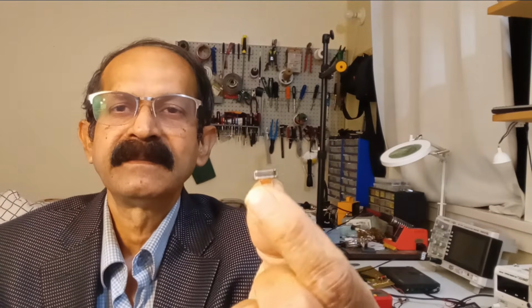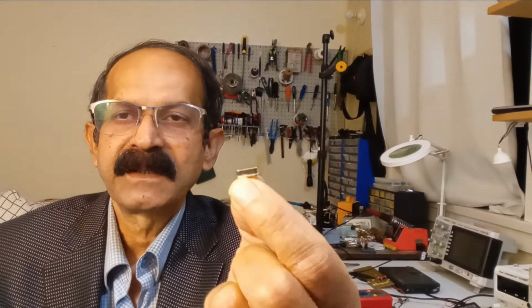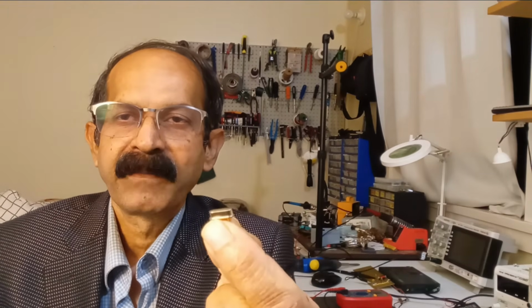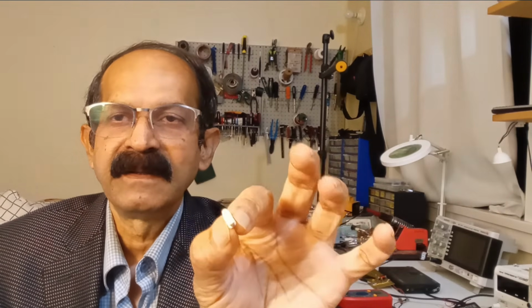network. If I use a crystal like this one, I have a small crystal in my hand, you can see. If such kind of crystal is used in the feedback circuit, the oscillator will oscillate exactly at the frequency written on the crystal. So I am using 27 megahertz crystal, and I'll show you how you can make one. And to detect the oscillation, you do not need an oscilloscope. So with an FM radio, you can easily detect whether your circuit is oscillating or not.